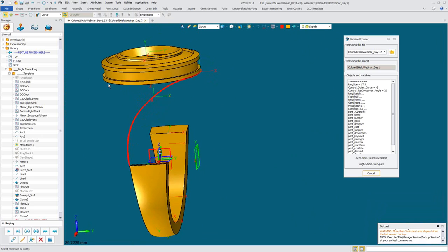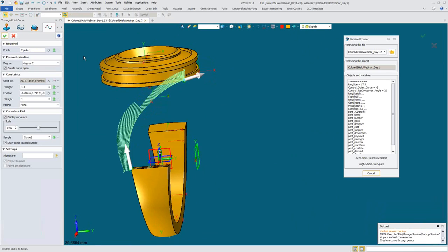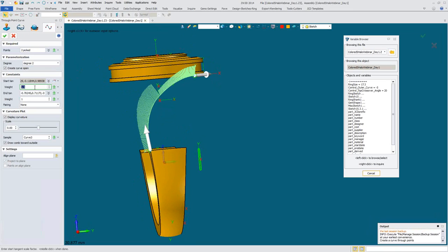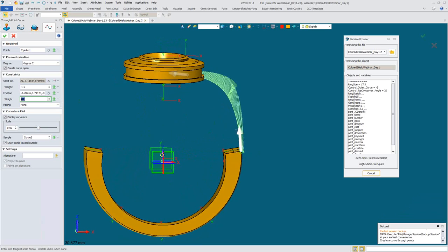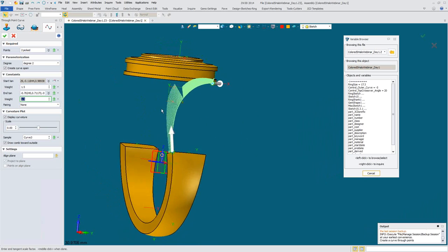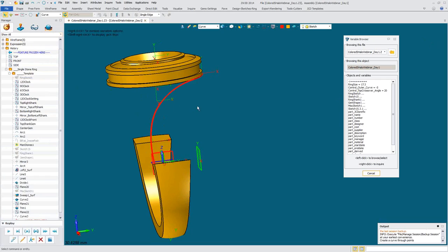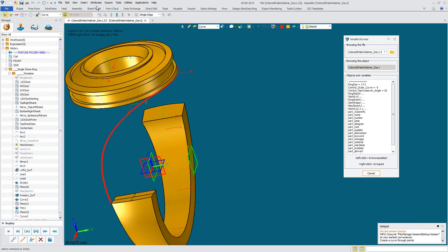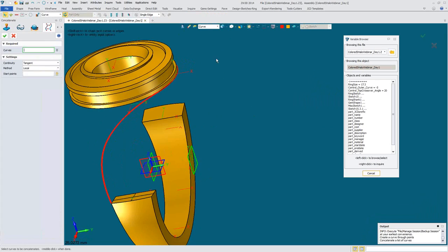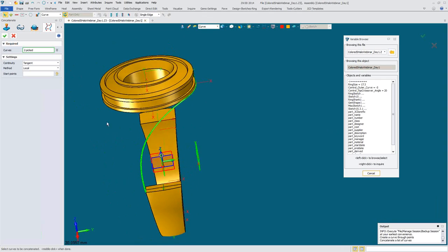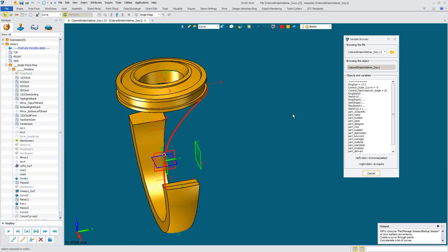Yeah, I'm not sure I'm liking that shape there. I'm going to right-click, redefine last, and I'm going to bump it up on here. Yeah, it's bowing out a little bit, but I'm liking this shape here. I'll leave this up to you guys. I'm going to concatenate this. Entity filter on curve. We'll pick 1, 2, and OK to command.